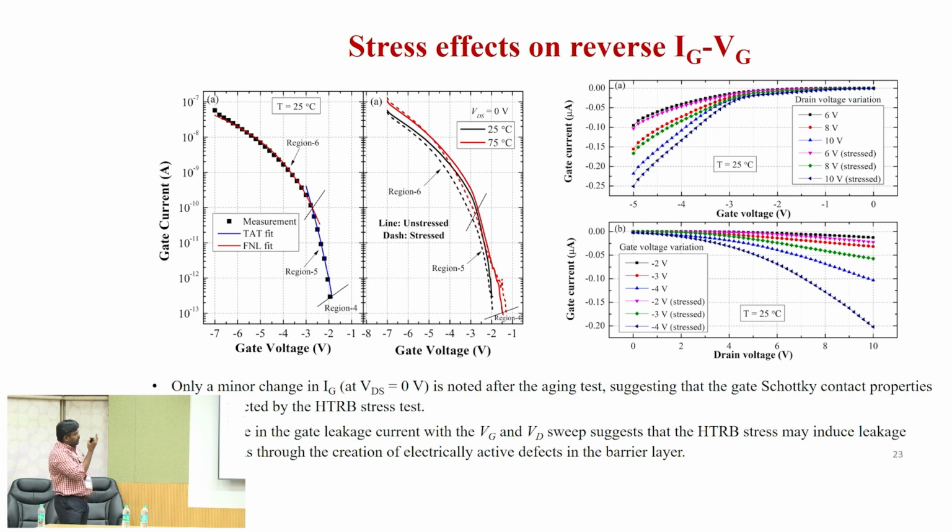So what we have done is we validated these IV characteristics, and we extracted the electric field profile from the simulations. Even IIT Kanpur has also observed this kind of behavior. Similarly, from the extracted electric field profile, we fitted the basic current equations. So at lower range it is trap assisted tunneling, then Fowler-Nordheim tunneling at higher gate voltages.